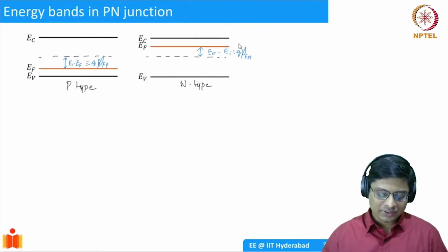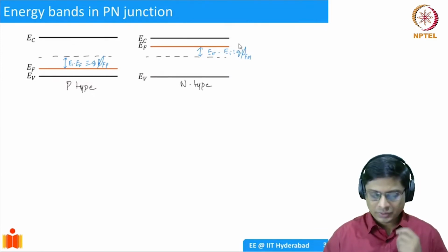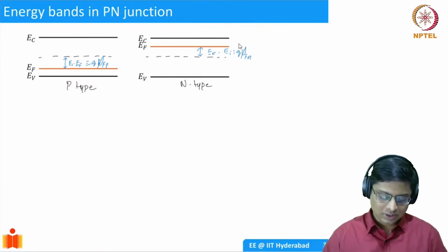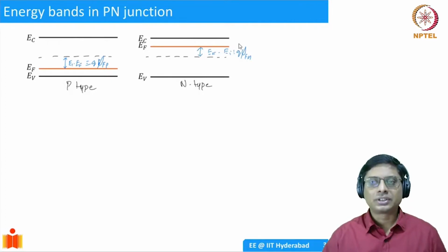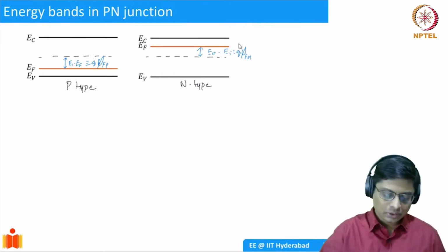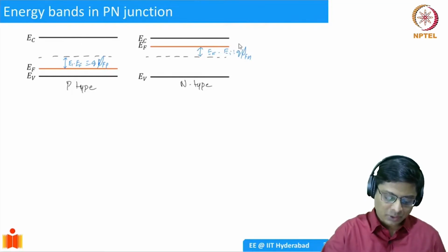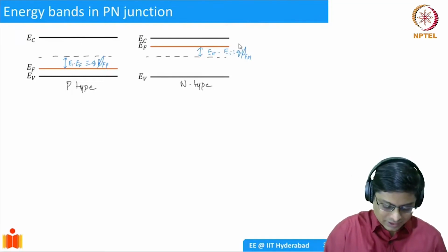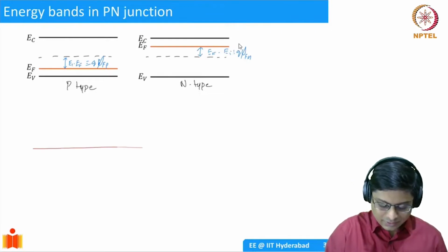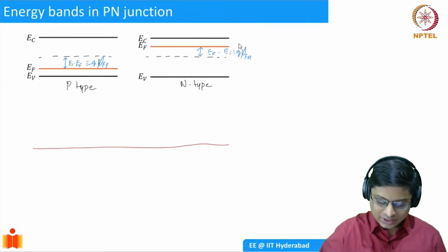So this is a regular semiconductor, right? Now how do we draw a band diagram? Well, these are in contact, they are not separate, right? When they come in contact, we have mentioned that under equilibrium across a semiconductor, the Fermi level has to be constant. There is no other electric field applied. It's just under equilibrium, so the Fermi level has to be constant. This we have seen a couple of times already. So let's start with that. I'll draw a Fermi level all across the device, and I'll say this is EF.